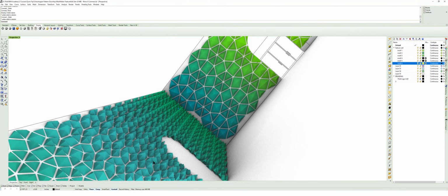I'm going to launch Grasshopper. And I'm going to put Rhino on the left and Grasshopper on the right. First thing I want to do too is go ahead and do a surface component. Right click, set one surface. And in the paneling tools tab, we want to go ahead and do grid surface domain length. I also, just as I like to try to put new surfaces in, I like to create a copy of this, reparameterize that, and then plug it in. So as we create more surfaces later, you can run it all into the same starting point.